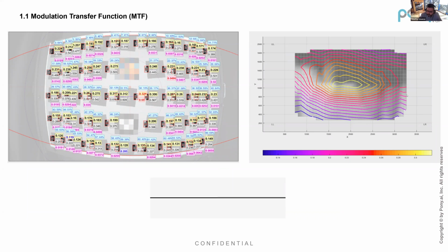But in automotive, we want a consistent map of sharpness across as much of the image as possible, because machine learning works on convolutional kernels, which search for features. If you had a line from center to an edge, then you would need a different convolutional kernel and a different neural path to detect the same feature, which just moves from one place to another. That makes more layers, and computational complexity grows extremely fast. And it's also harder to detect objects.